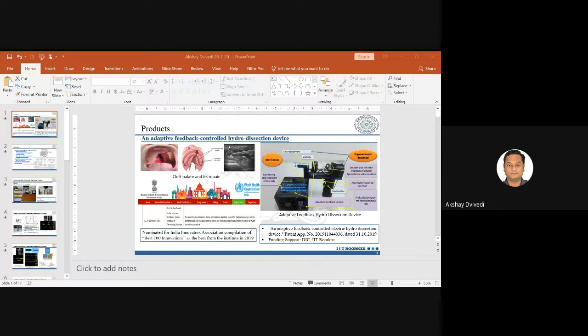So the idea here is, if I am removing that passivation layer, I am getting better consistency in that process. Some examples of this process are maybe certain microchannels. Here the dimensions mentioned are quite high, but of course this process can work and it can produce dimensions which are quite less, even in terms of 50 micrometer, 100 micrometer, those kind of things. And you can see the kind of cross section that has been created by this tool.